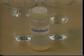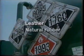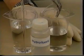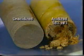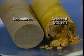Hydrofluoric acid has its own set of problems. From a safety standpoint, it reacts with leather and natural rubber, and therefore must be handled with extreme care. It is also the only common acid that will react with clay minerals, quartz, glass, feldspars, and carbonates. Tests have shown that HF concentrations above 4% tend to deteriorate cores to such an extent that they become unconsolidated and then plugged, resulting in a decrease in permeability.